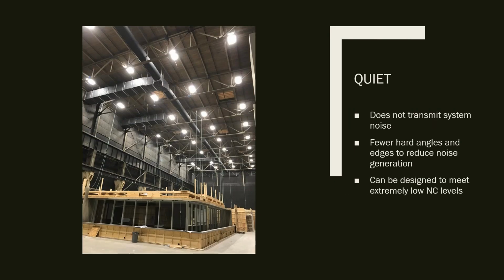So in terms of sound, textile systems do not resonate and transmit sound the way that metal systems do. If there's no sound attenuation in a metal system, the sound will travel throughout the metal and you would hear it in the room. Well, with fabric systems, if there is no sound attenuation, the sound will just break out right at the wall, right where the fabric connects to the unit. It will not travel and resonate throughout the fabric system.